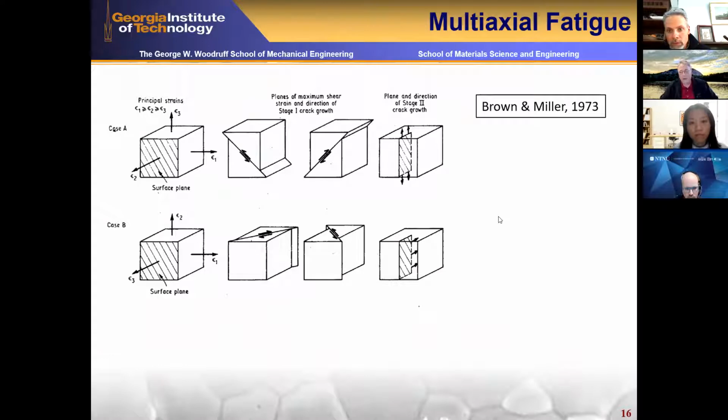I wanted to mention a little bit about multi-axial fatigue because this framework that I'm talking about is useful not only for comparing microstructures for a given loading condition, maybe uniaxial loading in the previous examples, but oftentimes when we have limited test data, maybe we have shear data, maybe we have some uniaxial data, we then have to go to a component that has combined stress states and make some estimate.